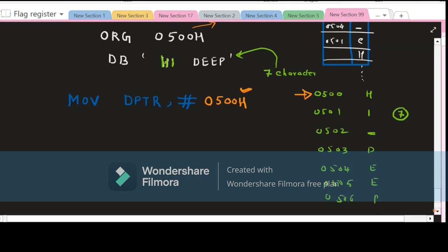So now after this, what we will do? Have a look at what needs to be done. So first of all, the first instruction I am writing is a very beautiful instruction. If you look at this instruction, you will realize what I am talking about. See, this is the initialization. The program is starting from here. Move. See what I am moving. Move into the accumulator the data 38H. Remember that 38H? The 38 is the initialization command to select your LCD. Is it clear to all of you?